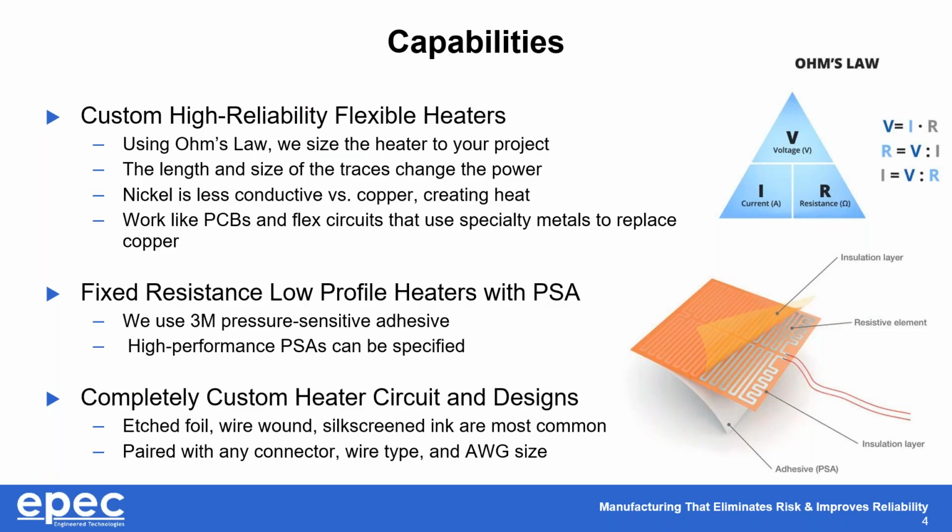Based on your power requirements or voltage input requirements, we customize every heater for your given application. The footprint of the heater can be changed, the shape can be complex, and overall, the actual length of the element within the heater and its cross-section is what drives the overall resistance value of the heater and therefore its power rating.